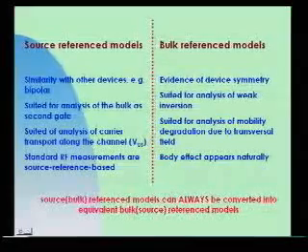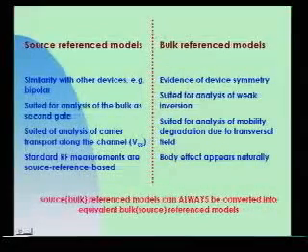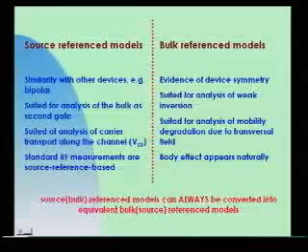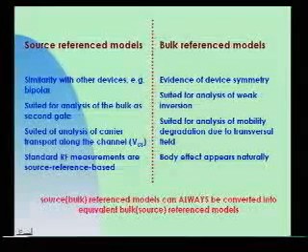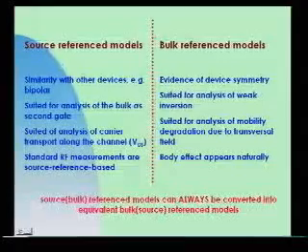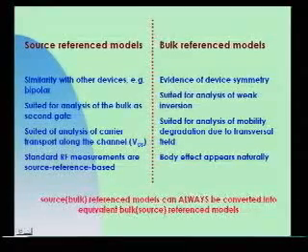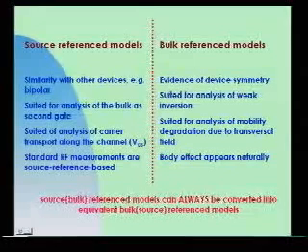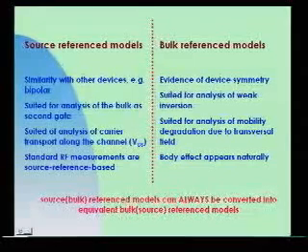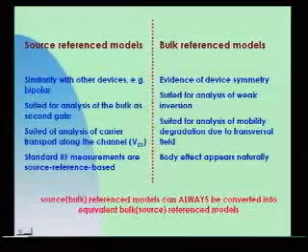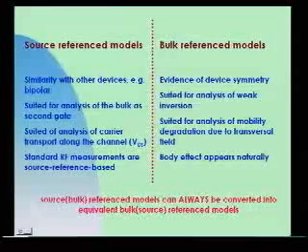Obviously, the symmetry exists when the layout is symmetric, because there are layouts that are not symmetric, but most of them are. The bulk-referenced model is more suited for analysis of weak inversion circuits and of the problem of mobility reduction due to the transversal field, the vertical electric field.